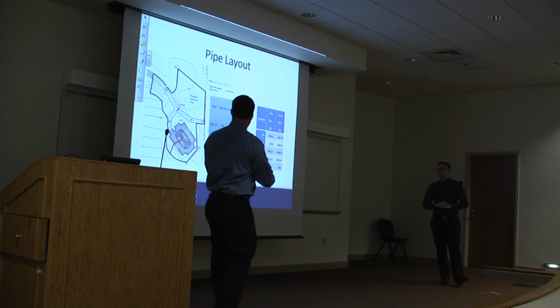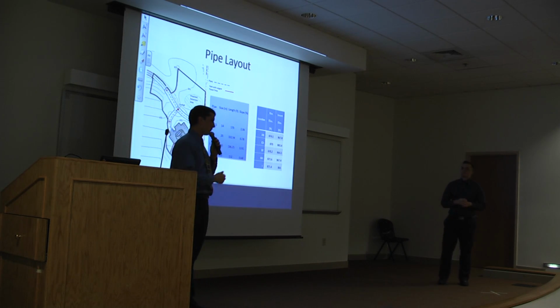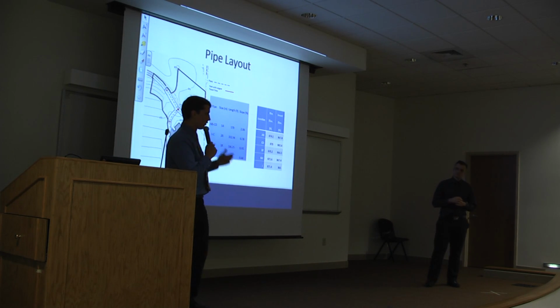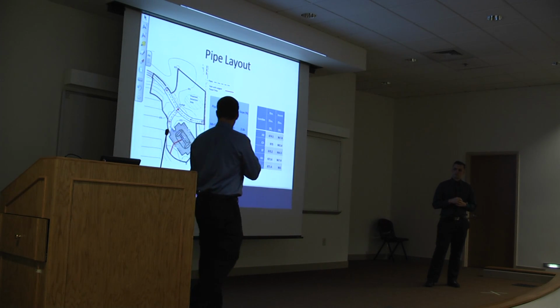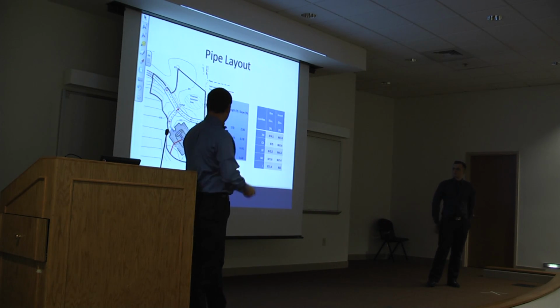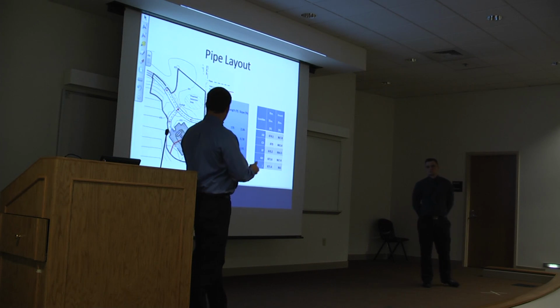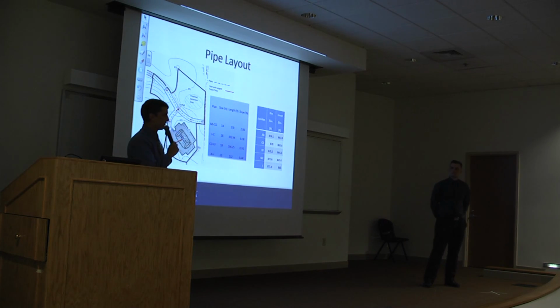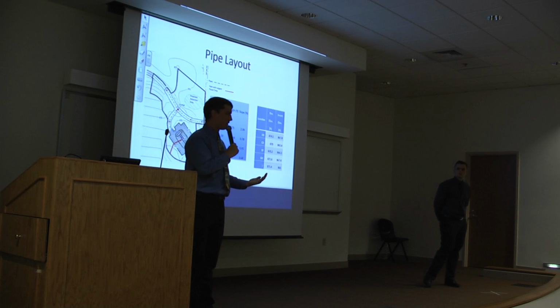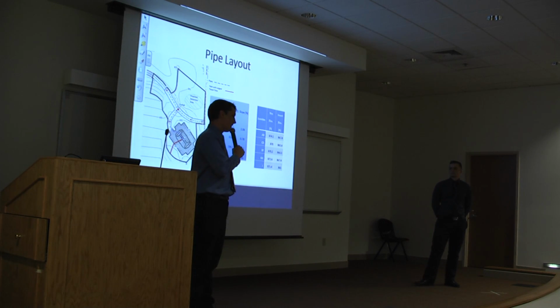We used different rates for the runoff coefficients and the Manning's number for the pervious pavement for the site. It decreased the amount of water that would be going to the detention basin. It infiltrated more water, so it helped. Because of the poor soil conditions on our site, it ended up helping out our model in the long run.